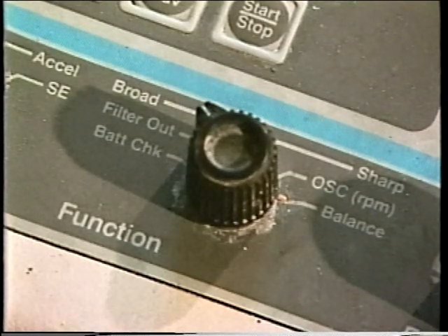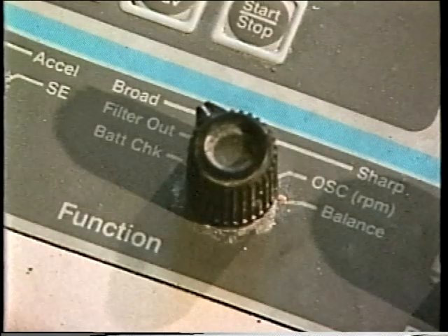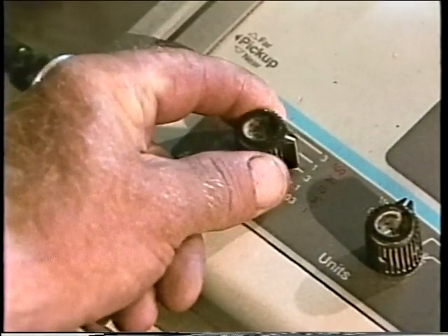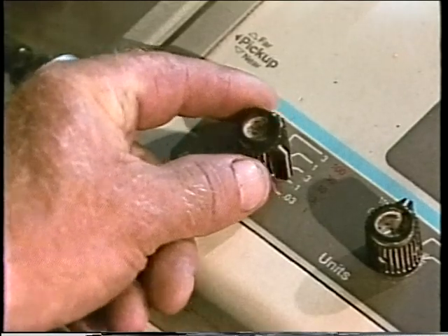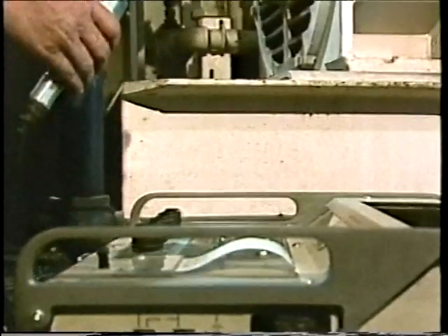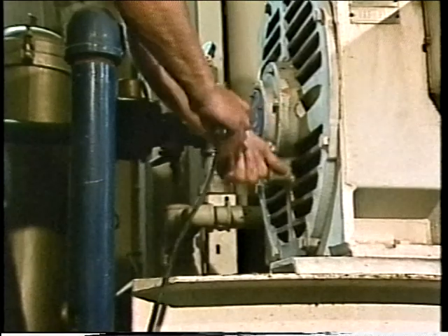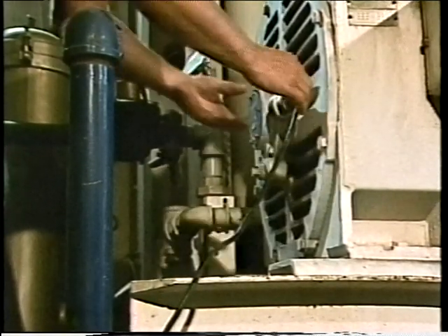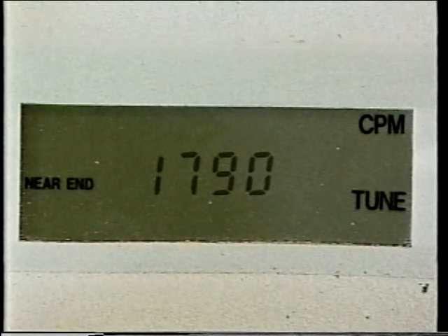On this analyzer, both the frequencies to be monitored and the scales for the indicator can be selected. As we saw earlier, it's a good idea to choose the highest indicator scale, then shift to a lower scale as needed. Once the settings have been chosen, the pickup can be positioned at the proper location, and the data can be collected. First, velocity is checked.